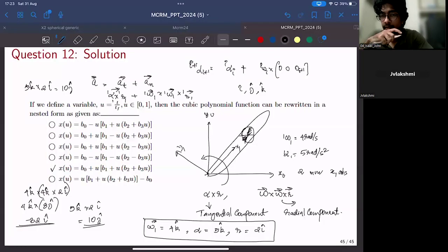Sir, centripetal acceleration is always pointing towards the center, whereas tangential acceleration is in the direction of motion. Yeah. So if you go by that, if you come out of those vectors, the centripetal acceleration is simply omega square r, and tangential acceleration is r alpha. So now in the r alpha direction, to draw the curve, it is in the positive y direction. So that gets plus, whereas the centripetal acceleration is pointing towards the negative x direction. So that gets the minus.